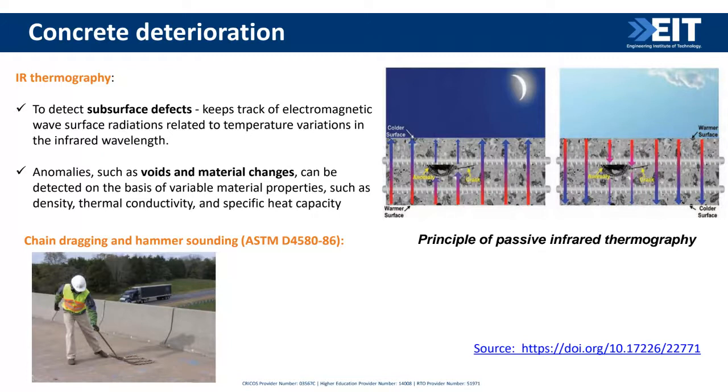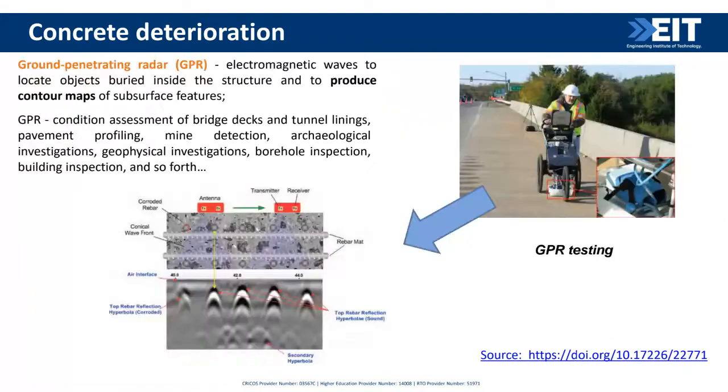It's interesting, the chain dragging, as you can see, it's a very simple test, no sophistication. If you compare the thermography with chain dragging, this is relying on the sound, right? You need to have a very skilled labor here, because it depends a lot on the sound when you are conducting this type of test. So here is more about sharing with you the type of non-destructive tests.